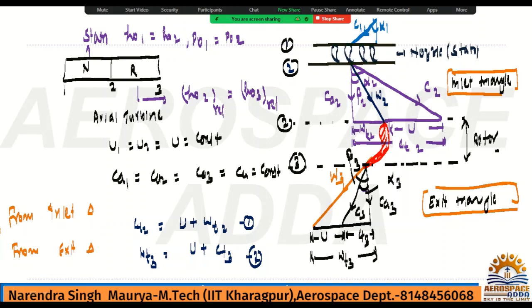Hence total enthalpy will be constant, and if you say it is frictionless, total pressure will also be the same. But in this case, your rotor is a work producing component. Rotor is rotating, so the enthalpy will be constant, but it's the relative total enthalpy, because it is the rotating part. It is rotating continuously. Anyway, you have also seen that in the compressor.